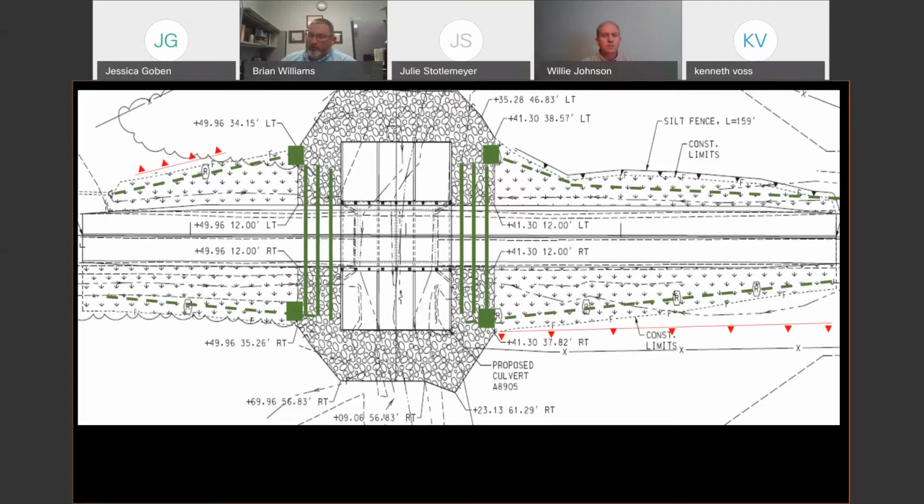Okay, you can't put silt fence around that toe because you can't get it in there. You couldn't install it, and you definitely couldn't maintain it. But you could look at some wattles or socks down that slope, some type of slope interruption BMPs that you could use to break that sheet flow down, slow it down, and capture that sediment as it goes down that slope. So consider that when you're looking at box culvert designs.